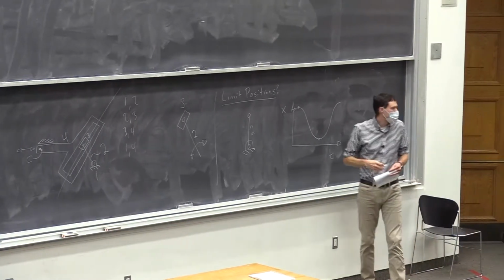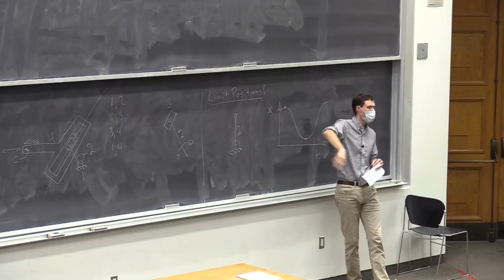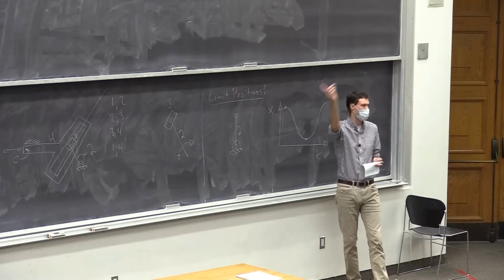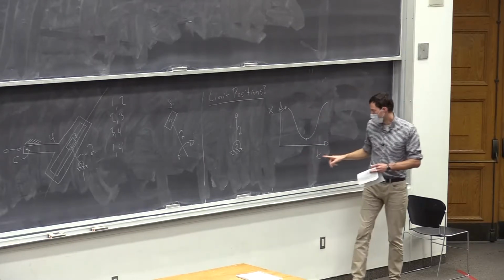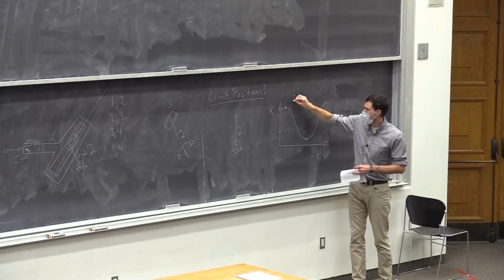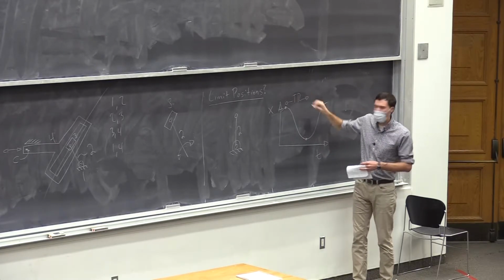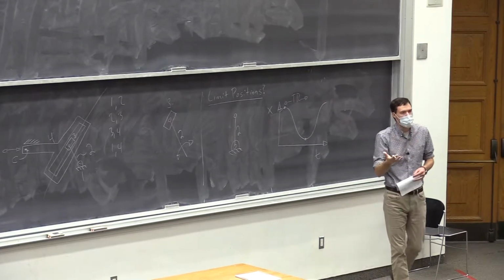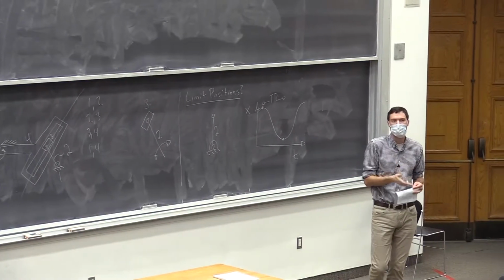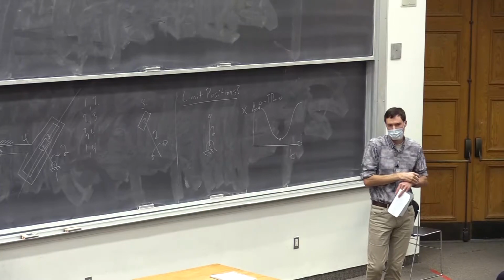Other mechanisms, like a rocker-rocker, the input has to turn around and go backwards. It oscillates, the input. But it's still important for something like calculating timing ratio, which I ask you to find. Timing ratio, right? You need to know how fast the input is going during that motion. So I say it's constant. So whenever it's moving at the same speed, that'll allow you to calculate timing ratio.